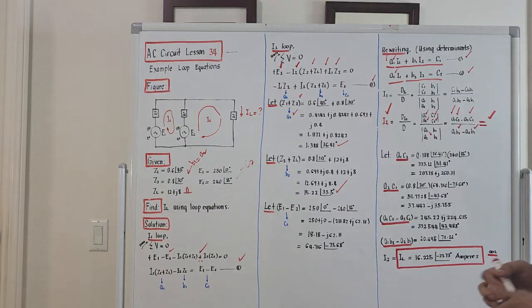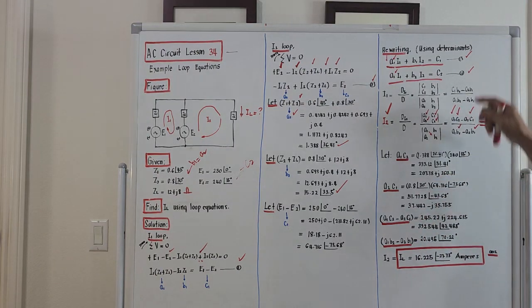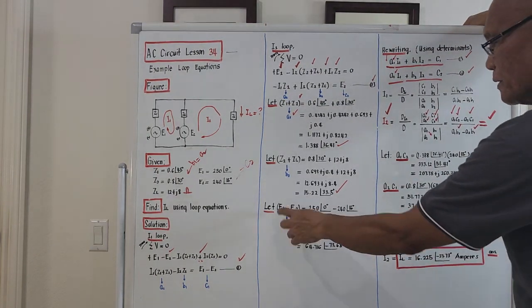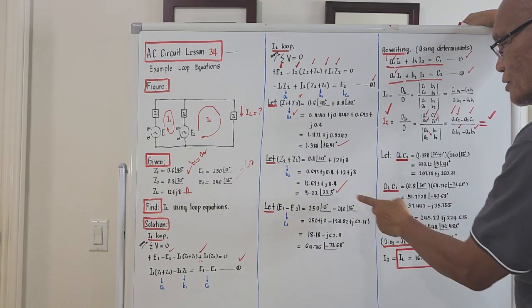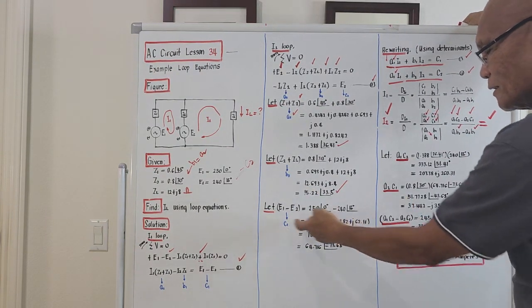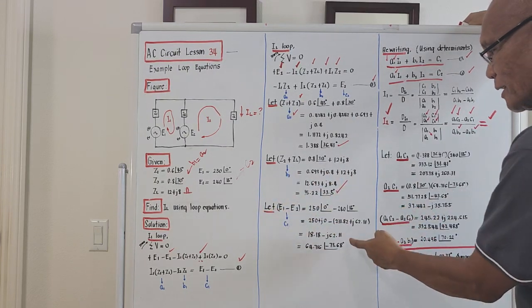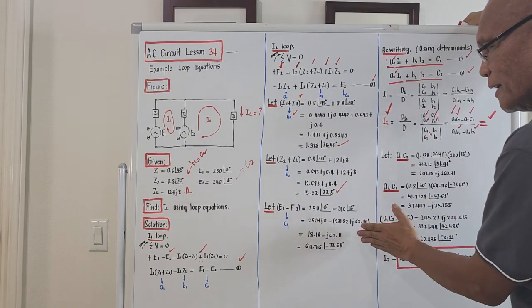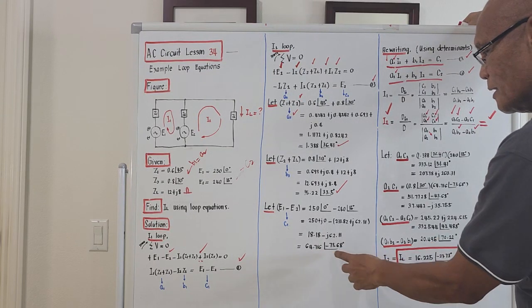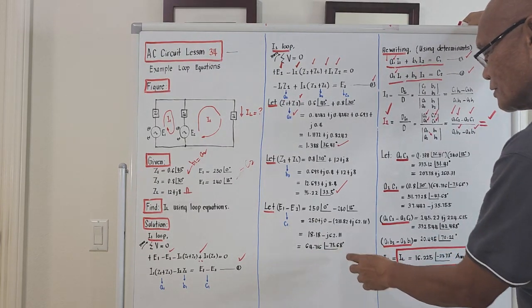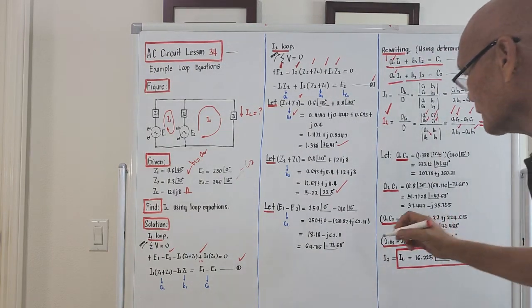How about the value C1? We need C1. It's the difference of A1 and A2. A1 is 250 angle 0. A2 is 240 angle 15. Subtracting this one, converting to rectangular, this is the rectangular. Again, converting to polar, 64.716 minus 73.68.